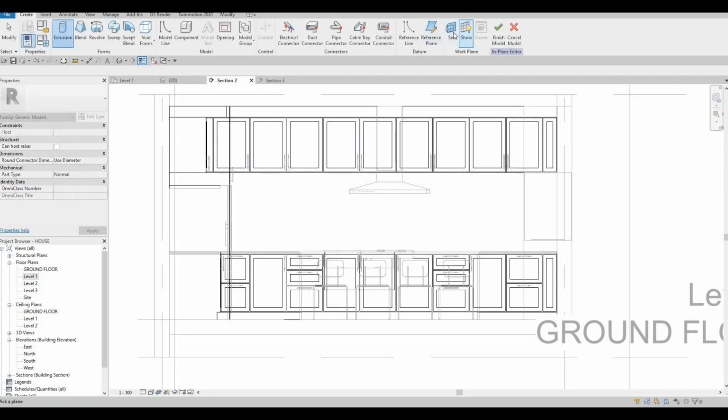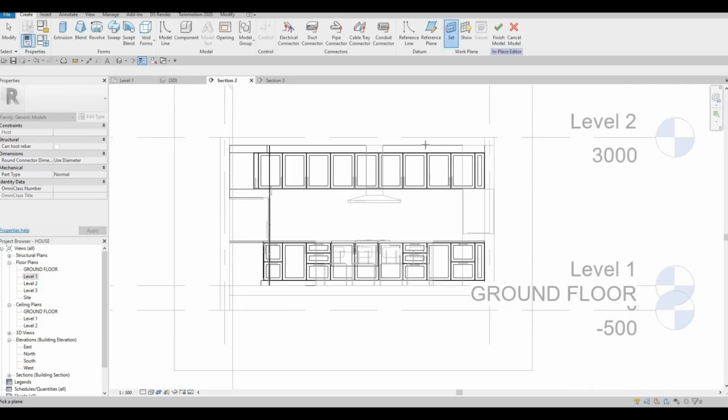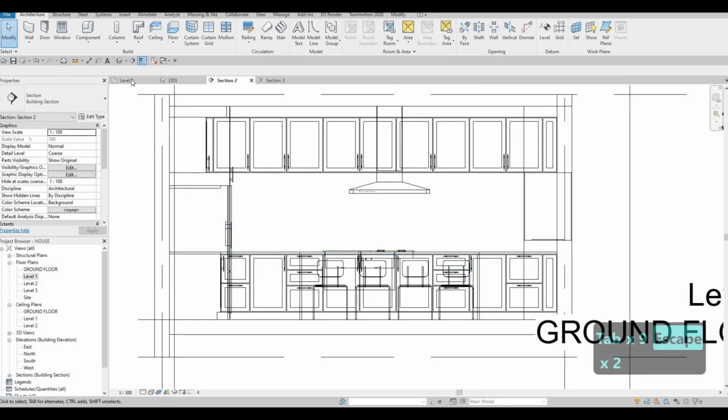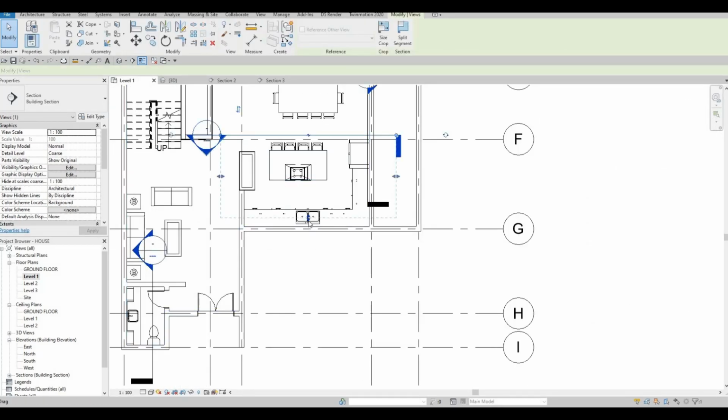We're going to set pick path, and then we need to select the wall. But before that, let's close this off because we need to know if this is all the way there. So that's why we weren't able to select the wall, because the view range is off.